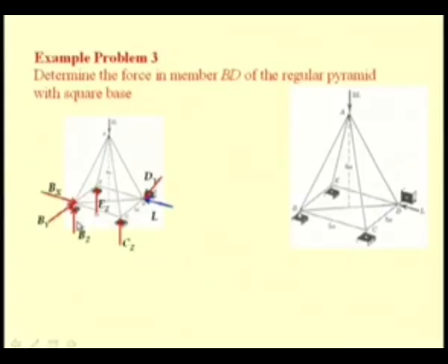If we see the joint at B, we have to determine 3 unknown reactions and then the various forces, that is BC, BD, BE and BA. At D, we have to determine only one external reaction Dy and the forces in the members AD, CD, BD, ED, etc. At D, we see that we have to determine forces in 4 members, and in order to do that, we need to know at least one force if we have to use the equilibrium equations of joint D.